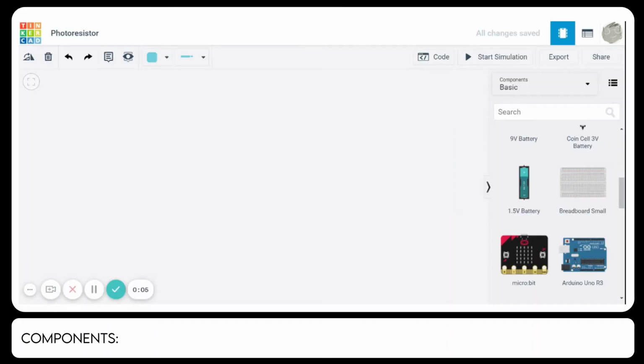We're going to talk more about the photoresistor. Basically, the photoresistor, or the light dependent resistor, sometimes abbreviated as LDR, is a photoconductor. It is a special resistor made of a semiconductor material such as cadmium sulfide or cadmium selenide. Its working principle is based on the internal photoelectric effect. The stronger the light, the lower the resistance value. That's why the LED gets brighter.